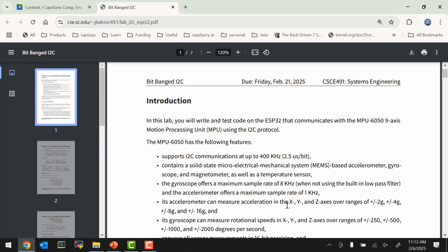One nice thing about that is you remember how much trouble you had talking to the FPGA in 3.13? A lot of times it wouldn't connect. The reason is that the FPGAs use this USB Blaster type interface, and the way it works is it directly writes to a file in Linux, /dev/bus/USB/ the USB controller number / the USB device number. That's a device file, and you just write to it.